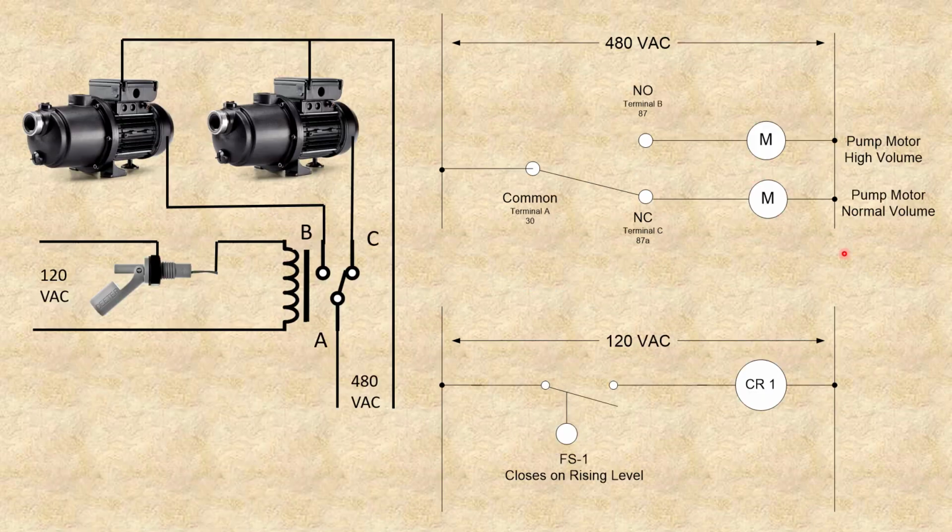Here's another example of maybe how it looks in the real world. This is a level switch, and the way this works, actually there's a magnet in here, and when the level of the fluid causes the float to move up, because this is buoyant, whenever that comes up, the magnet will cause these contacts to close. So this is operated by level, but through a magnetic connection.